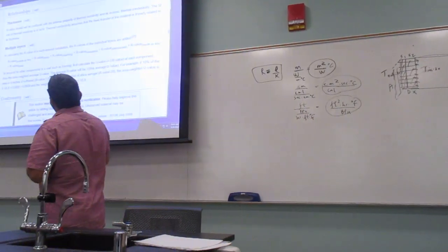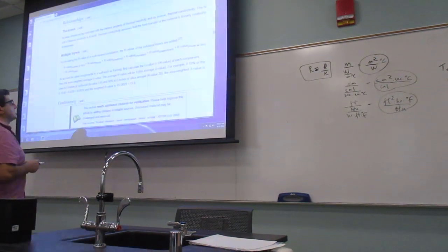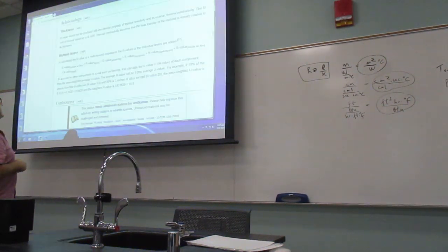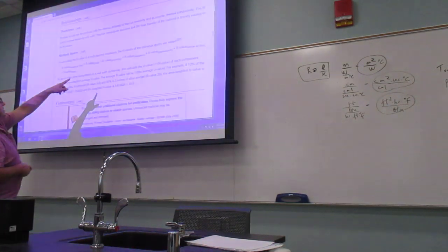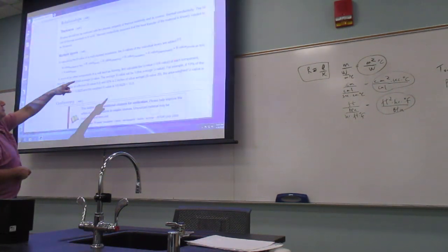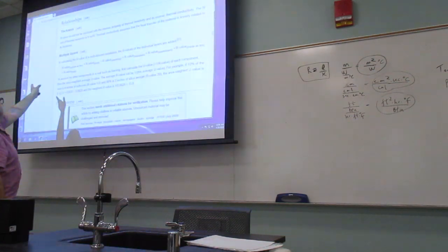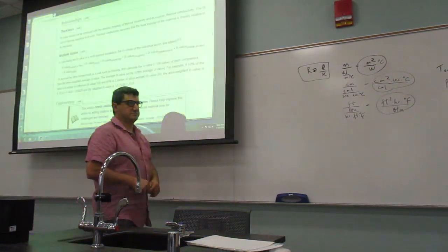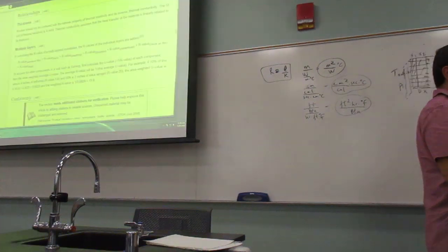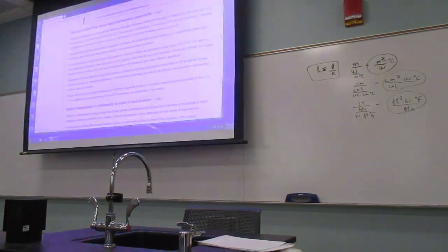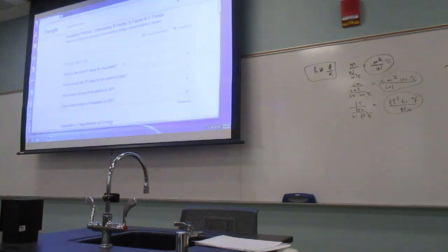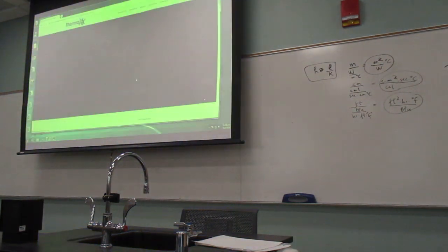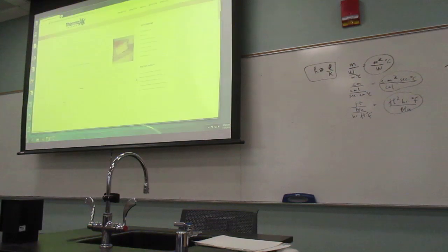In calculating the R value of a multi-layered insulation, the R values of the individual layers are added: R value outside air film, R value brick, R value sheeting, R value insulation, R value plasterboard, R value inside air film. Whole. So now we could look at some of those other places where it gives us the actual R values of different materials.